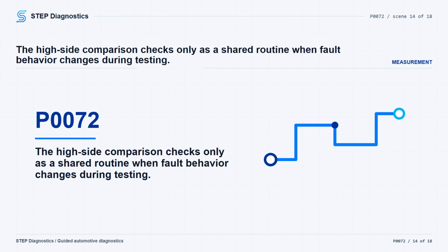If voltage data is not available, watch for the circuit low fault to set with the jumper in place. Then check the resistance of the temperature sensor signal circuit and the temperature sensor ground circuit. Typically, the circuit resistance should be less than 5.0 ohms.